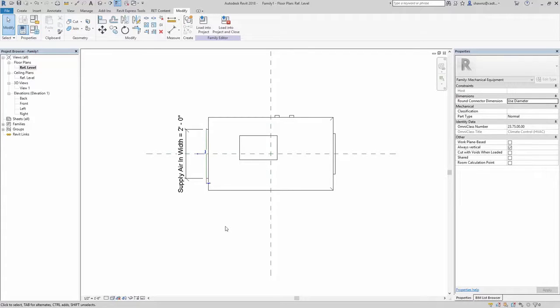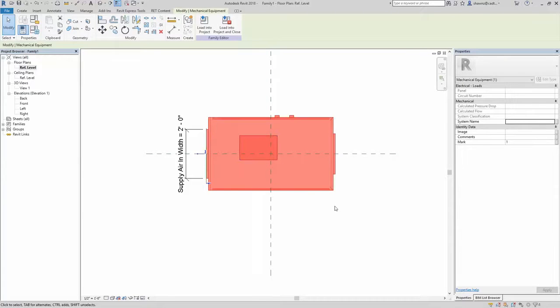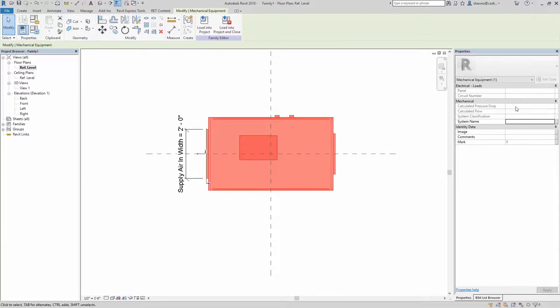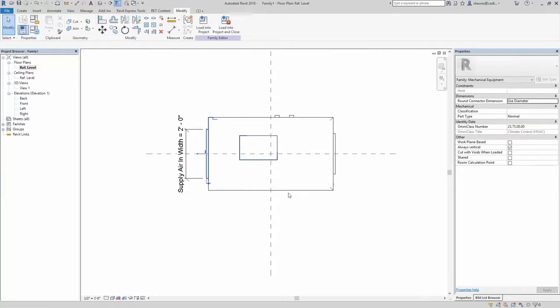Now, Revit is actually pretty efficient with regenerating 3D graphics in plan view. I still try to go ahead and have a 2D graphic for these pieces of content when I bring them in. So I would take this object here and probably hide it in a plan view if I can. In this case, it doesn't look like I have those visibility settings over here to be able to do that, unfortunately. But it would be nice to be able to hide that in a plan view and then just put 2D graphics out here. So there might be some limitations on this. I mean, I'm not going to use this for every piece of content. I'm usually going to try to model it myself from scratch if I can, but I can't always do that.